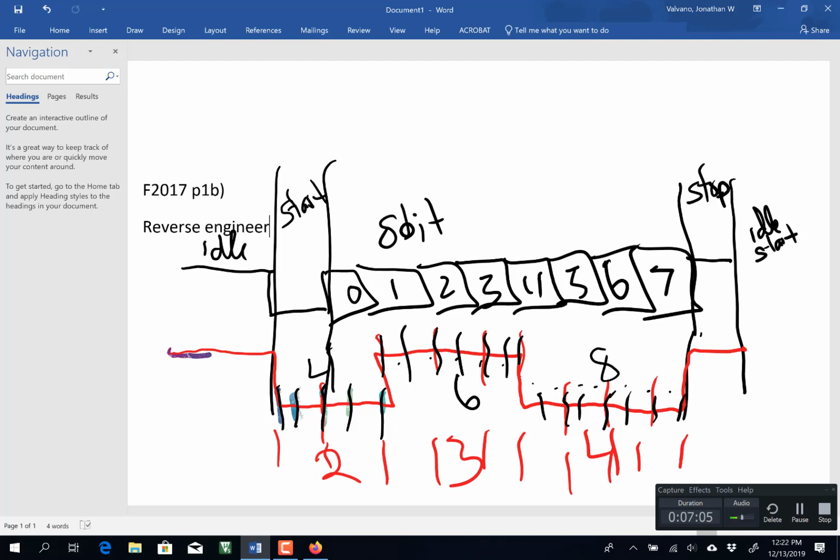And once you figure out the ticks, now I can associate it with the top waveform to figure out the bit pattern, which here it's got in reverse order. This one here is a 0. I got 2 1s, and then I have 3 1s, and then I got 4 zeros. All right, so that's a 0x0E.